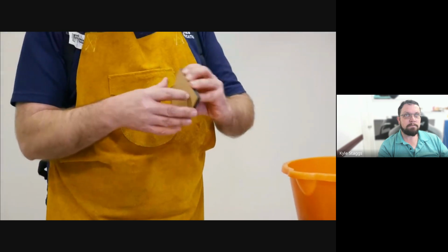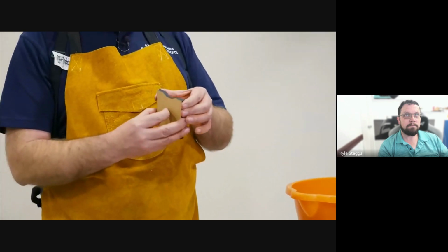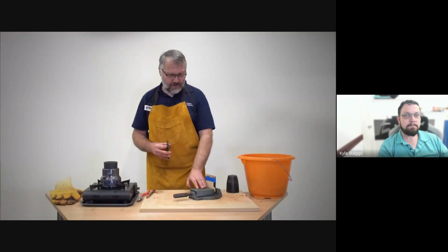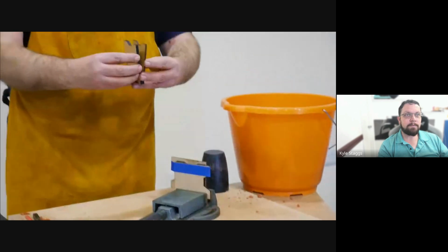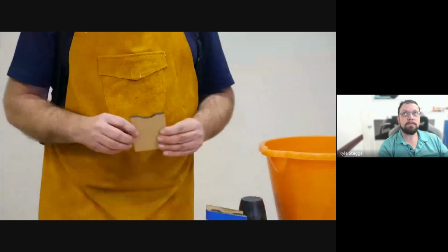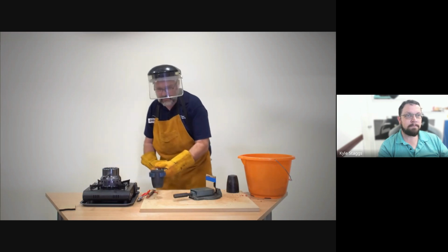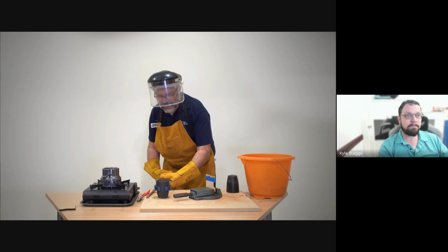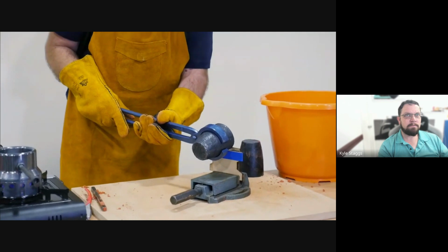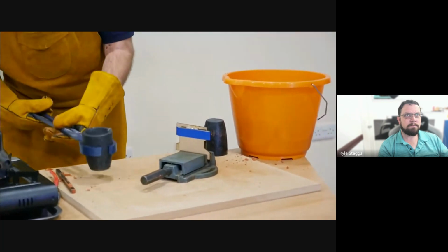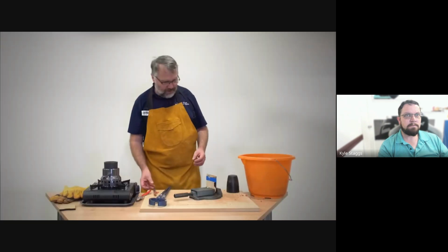They locate together and have a board backwards and forwards, just so that you've got somewhere to pour the metal. It's held in a machine vise so that it's nice and stable, and we've got a bit of tape around as a secondary clamping so that nothing splays apart when the metal is poured in. And this time it takes quite a steady hand as we're dealing with a fairly small target to pour this metal. And then just to make sure that there aren't any air bubbles, a few gentle taps will hopefully give a good result. Right, so we've given this a few minutes to cool down.